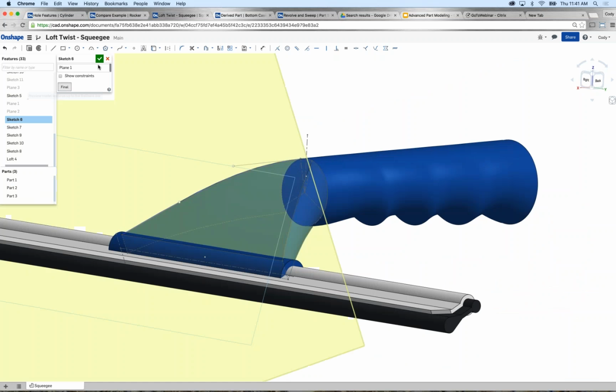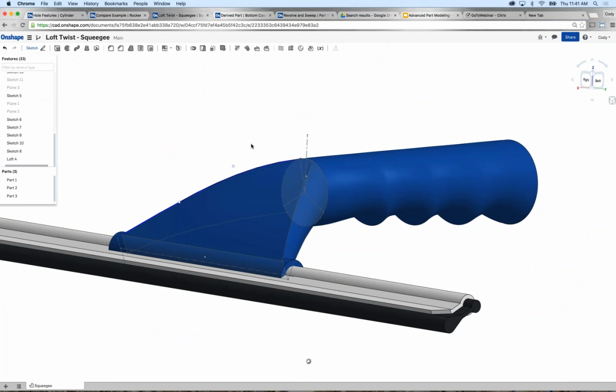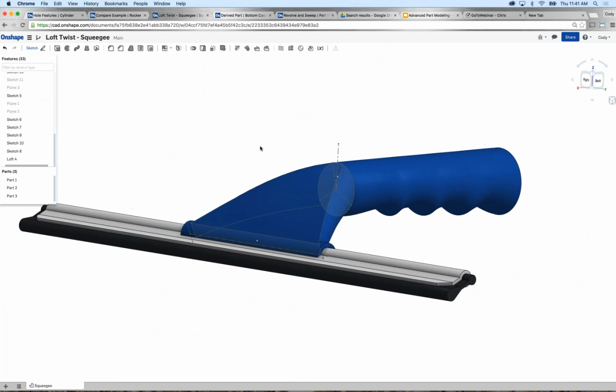So that is the final, and that is lofts. In general, I'd recommend if you want the utmost control, make sure you have the same number of vertices between profiles so you can split them up. And if you really, really want a lot of control, guides give you that. Now, in conditions can do a lot. So in conditions are simple and they give you quite a bit of flexibility, but guides are kind of the ultimate. So, all right.